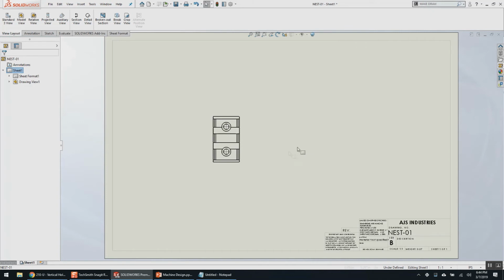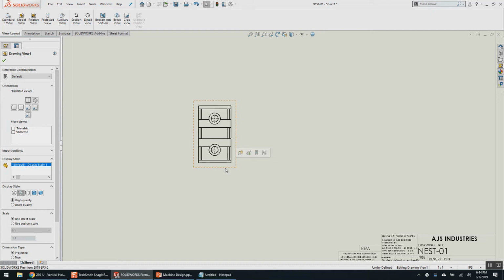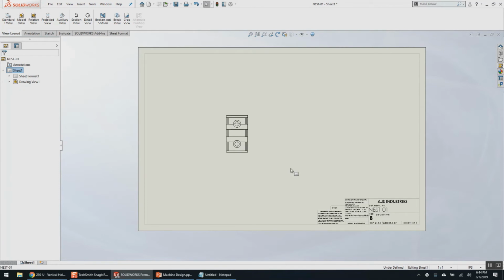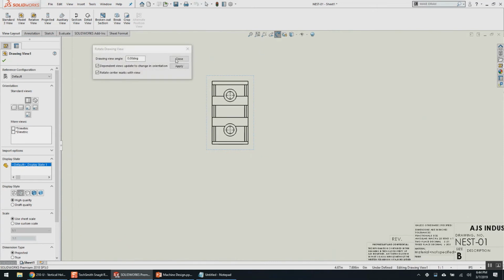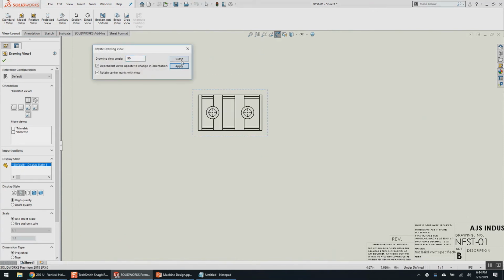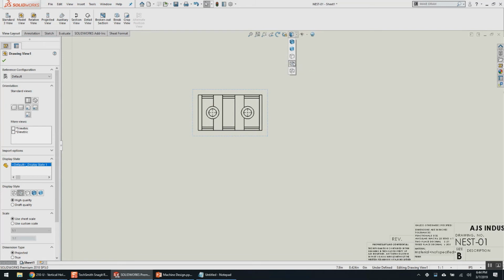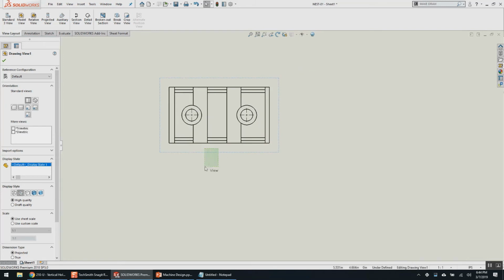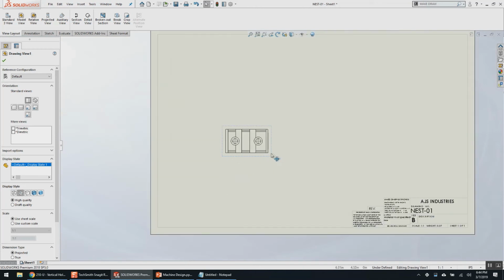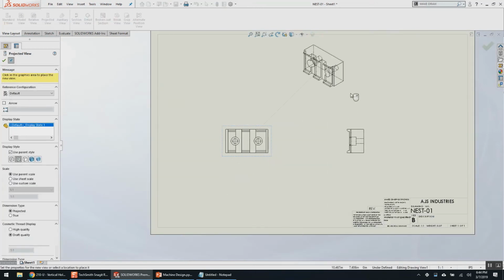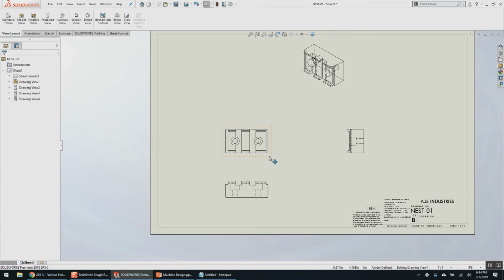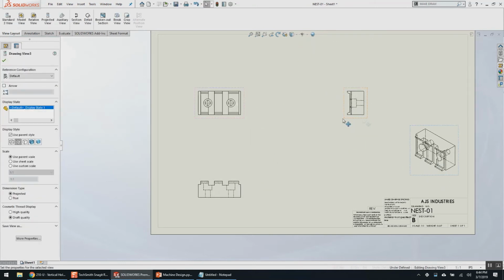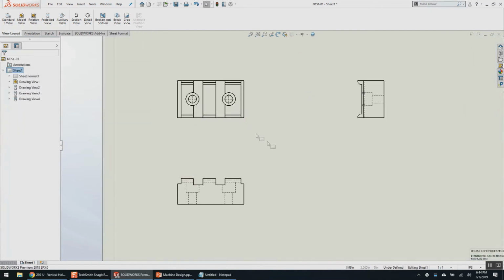Real quick power rant on how to do drawings. Always make the details horizontal if it's not square, because it fits in vises that way. No machinist, realistically, puts their vise on sideways to hold a part like this. So click on the part, click rotate, do your 90 degrees, hit apply and close. And then also change this to hidden lines shown, which it is. So now that it's rotated the right way, I'm gonna click on it, do projected views: project over, project ISO, project bottom, and there I have an actual manufacturable print in that context. So let's save this real quick.